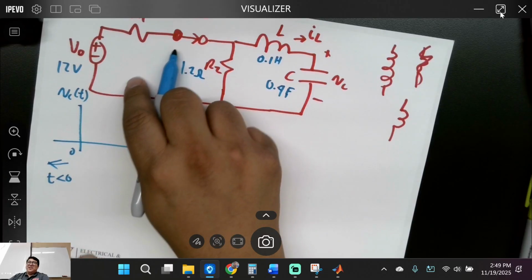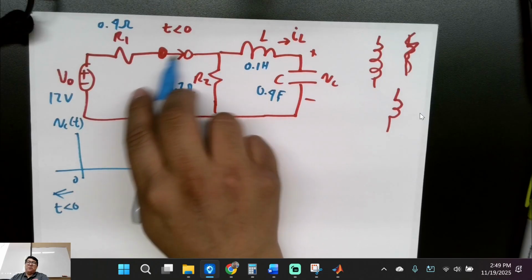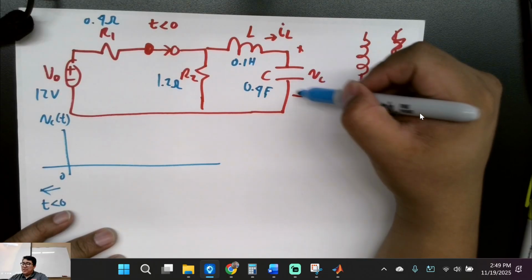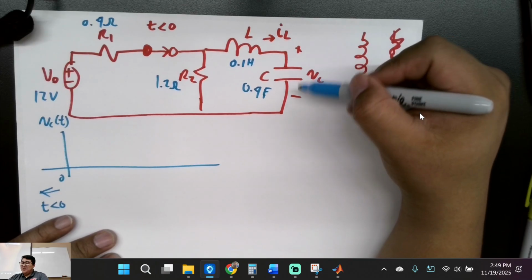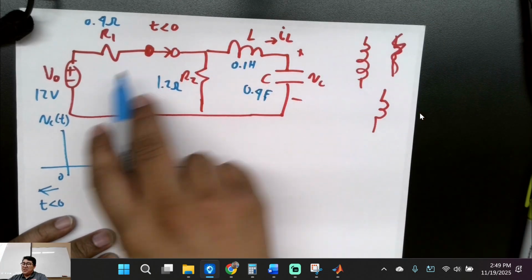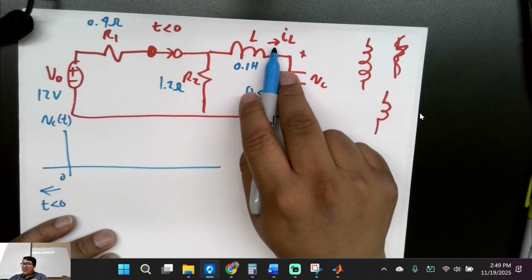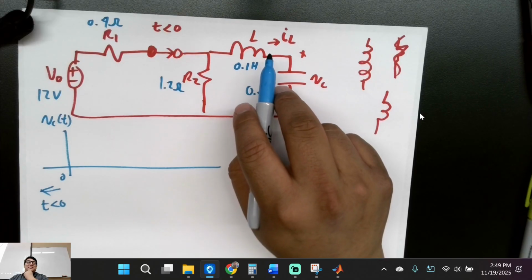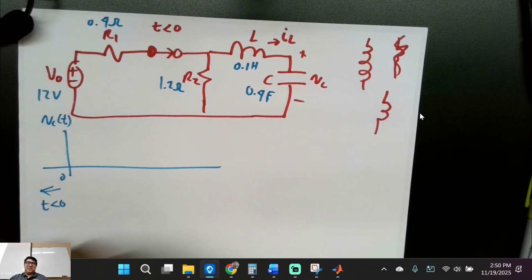So we know that the wire is closed. This right here is just the wire. What's the voltage over here? Capacitor DC? Actually, better yet, what's this inductor at DC? We have current going through here. Over long periods of time, what does the inductor act like? It's the wire. It's a short.